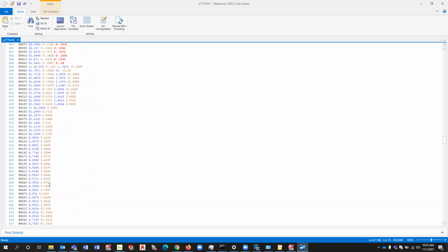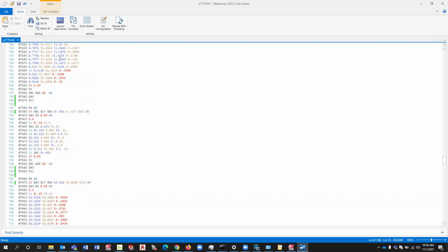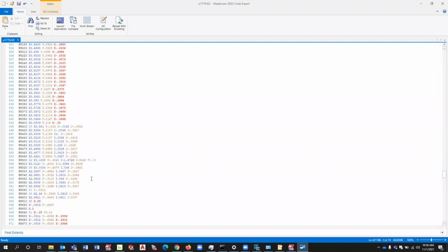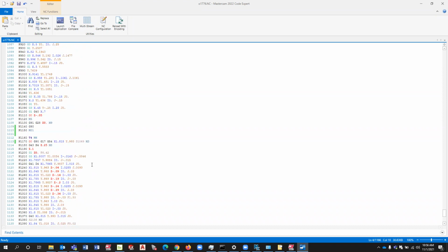Dynamic milling can cause these numbers to kind of get out of control. So think about the process of how you're removing material. Sometimes just doing multiple contours is quicker and also easier to digest. All right, I believe this program looks good.